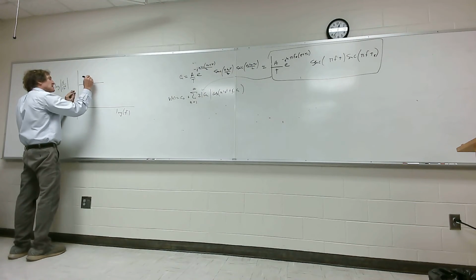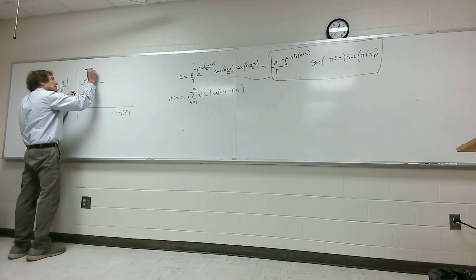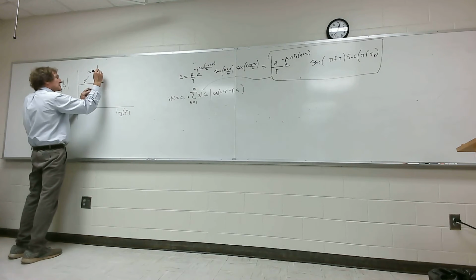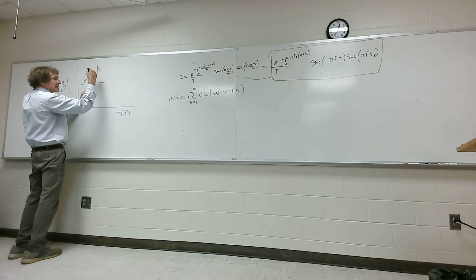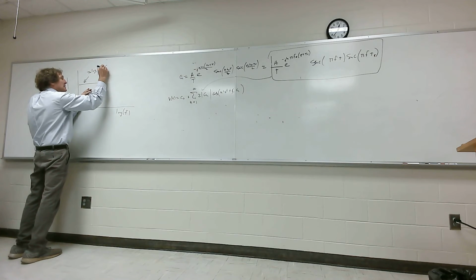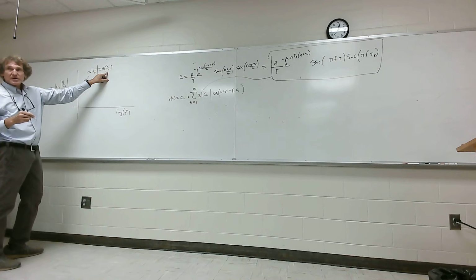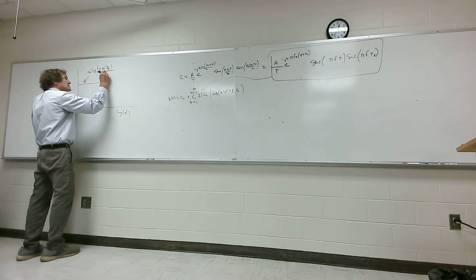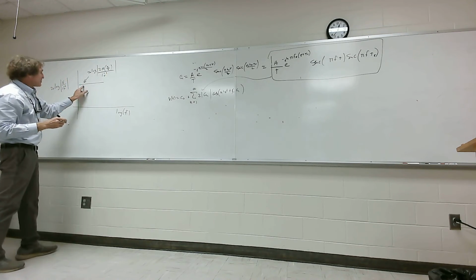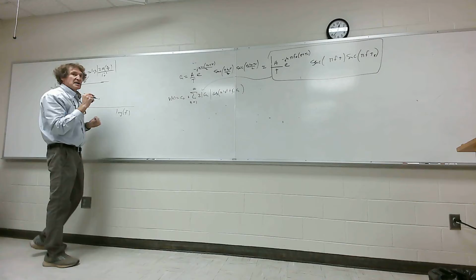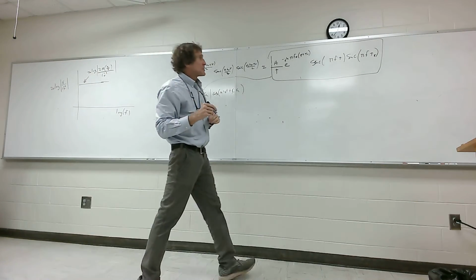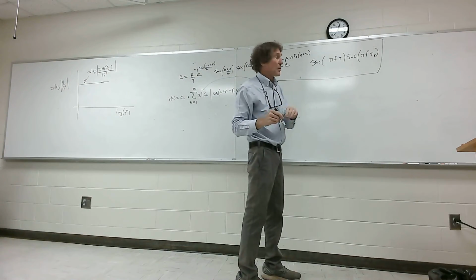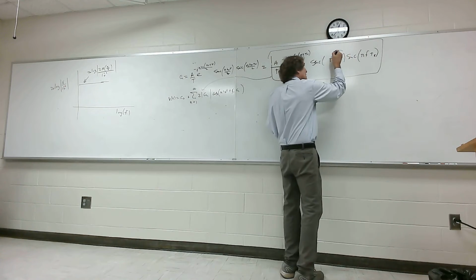It's going to stay at a value, please write this down, of 20 times the log of the magnitude of 2 times the coefficient A times tau over T. Usually that duty cycle is going to be 1/2, so it's really just the log of A, and then you divide that by 10 to the minus 6. So that will be this line. It'll be flat until the first break frequency, which is this one.